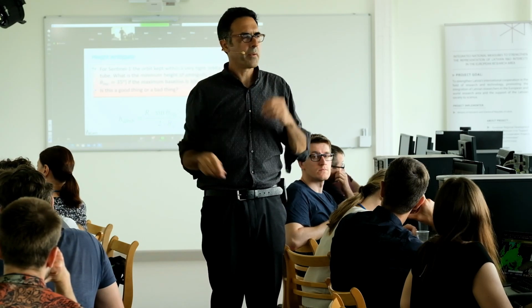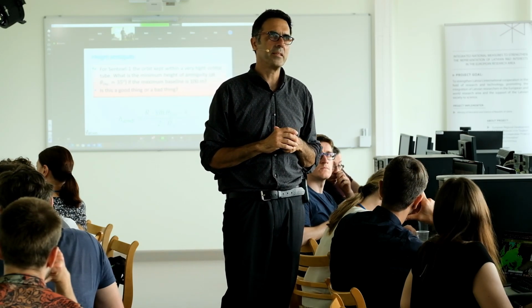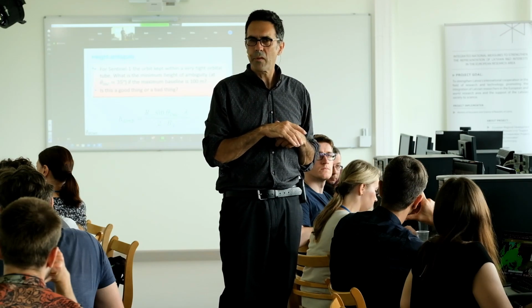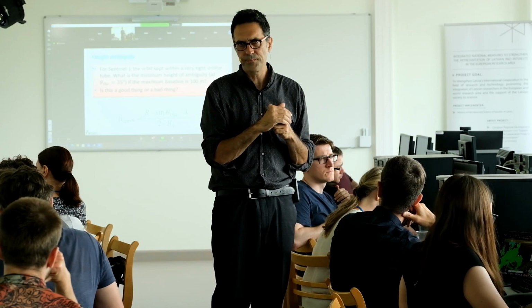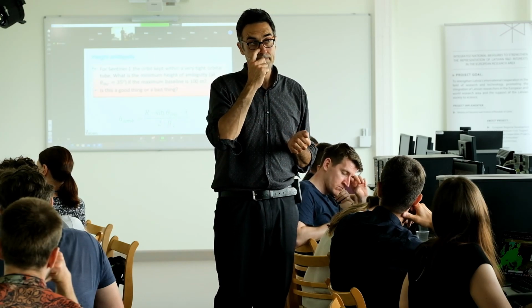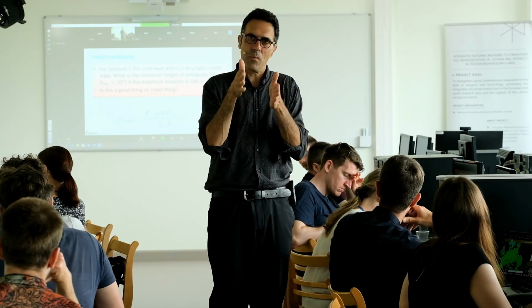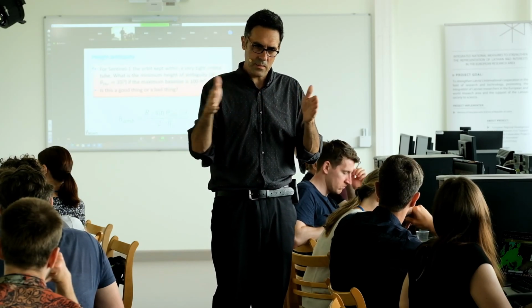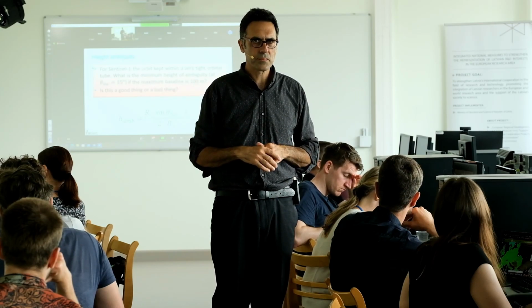There's a whole signal processing part of that, so I'll let you first have coffee. But the basic thing is that, say, for Sentinel, that would be maybe a couple of kilometers. So if the baseline is a couple of kilometers, at some point we start losing points. Flat areas, we lose faster than point sources. This is why we steer that satellite to be very close to the nominal orbit, only the 100-meter orbital tube. Because the longer the baselines, the more sensitivity, that's good, but it also introduces noise.